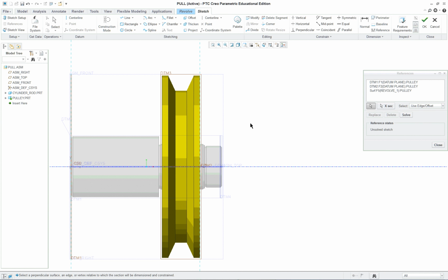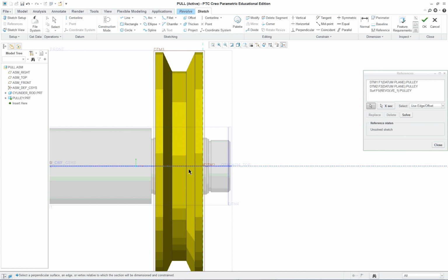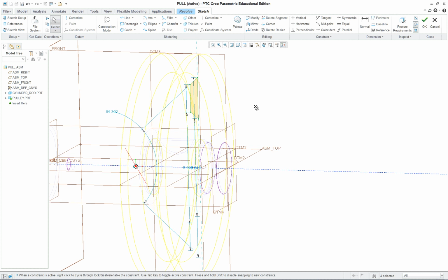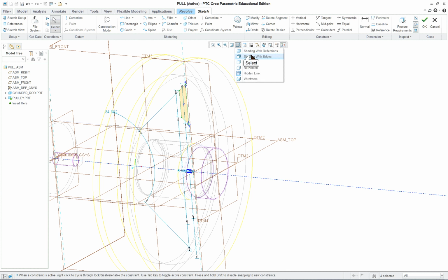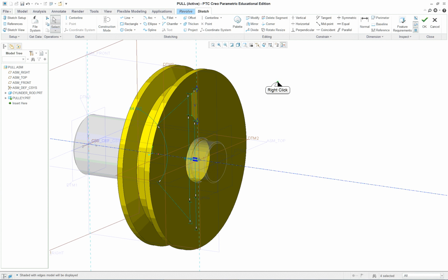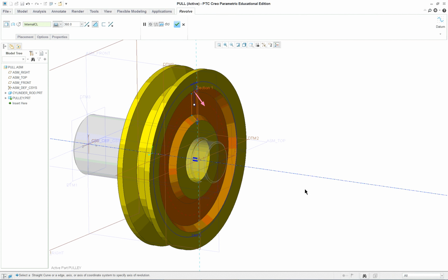On the outside here, probably the main one that I need. I don't think I need any other one. Close. And I'm going to put this into a hidden line and then do my sketch. So I'm going to sketch in here. So this is nothing more than a revolved cut to create. I'm going to close it so you can see it. So there's my construction. The yellow wasn't a good choice, was it? So right mouse button, let's see what happens. Click OK, and there's my cutout.